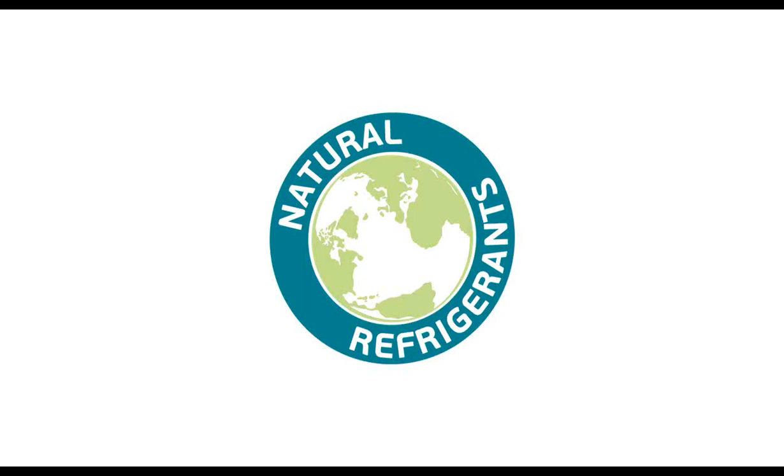Let's see. Oh, here's a good one. Can standard recovery units safely be used to remove hydrocarbon refrigerants from a system? That's a great question, actually. To recover the refrigerant from a hydrocarbon system, you need to use a system that is approved for hydrocarbons because of that spark potential. So that recovery system needs to have all the safeties associated with recovering hydrocarbons, such as all the spark-proof components in it.